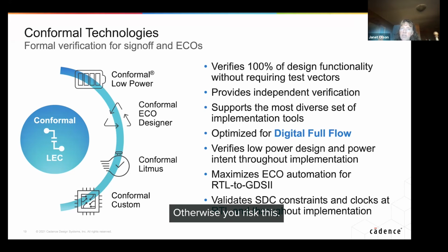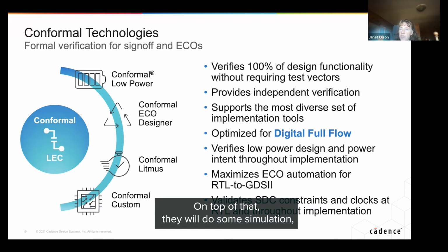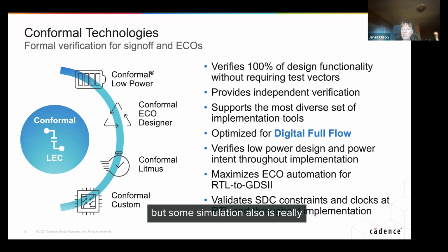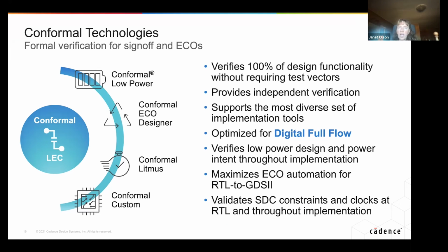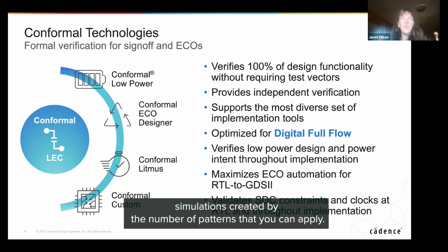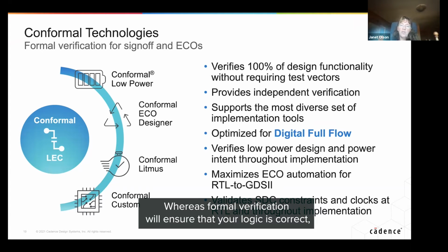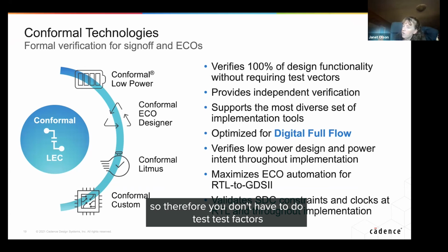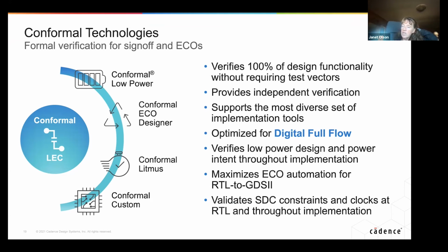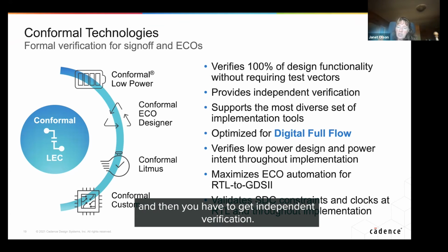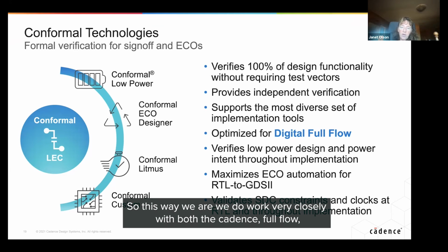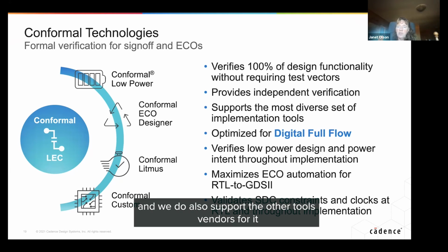Otherwise, you risk this. On top of that, they will do some simulation, but simulation is gated by the number of patterns that you can apply, whereas formal verification will ensure that your logic is correct. So therefore, you don't have to do test vectors, and you get independent verification. This way, we work very closely with the Cadence full flow, and we also support the other tool vendors for it.